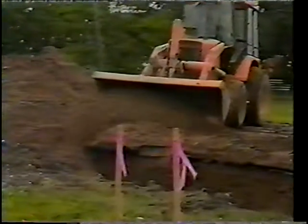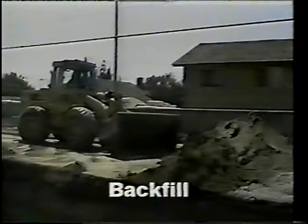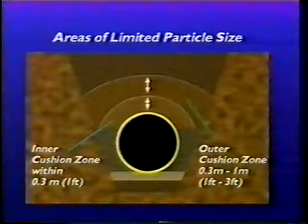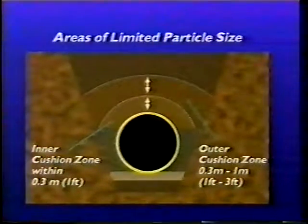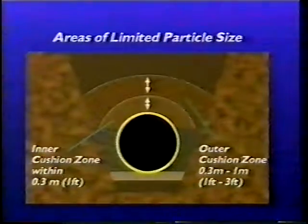Soil excavated from the trench is used for backfill where possible. The economic advantages are obvious, but debris, large rocks, or organic material will need to be removed. However, soil types may be specified for 2 cushion zones nearest the pipe. Here, the maximum particle size will be limited.